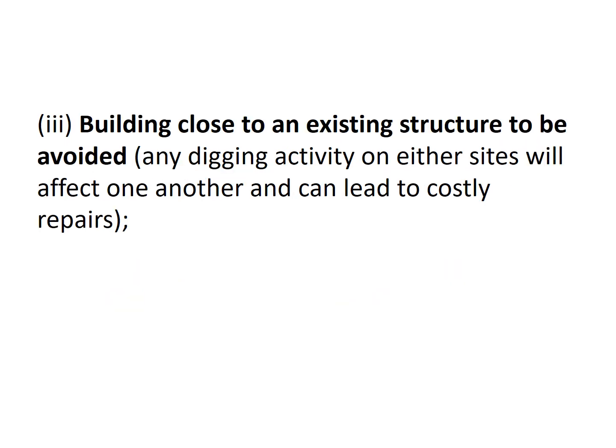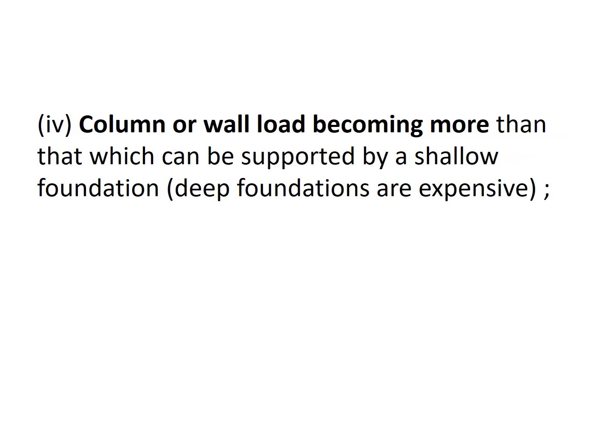Building too close to an existing structure is to be avoided because of the extra cost of pinning, and any digging activity on either site will affect one another and can lead to costly repairs to the neighboring site, obviously. Some column or load bearing becoming more than what can be supported by a shallow foundation. So deep foundations, as a rule of thumb, are expensive, much more expensive.